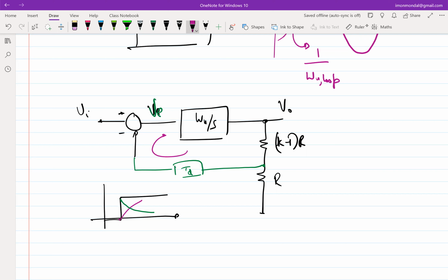So essentially, if you have delay in the loop, intuitively you can assume that there can be some case where the output overshoots, because of the delay, the error voltage is coming after some time. An extreme case is that if delay is infinite, then your output will keep on ramping. There is no feedback, right? But if the feedback eventually comes, then you might correct and you might undershoot, you might overshoot, and so on. These things can happen if you have delay in the loop.